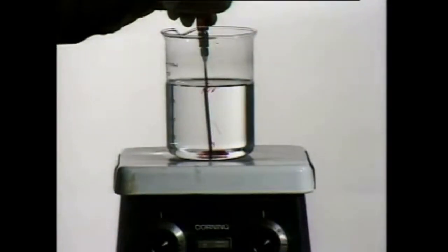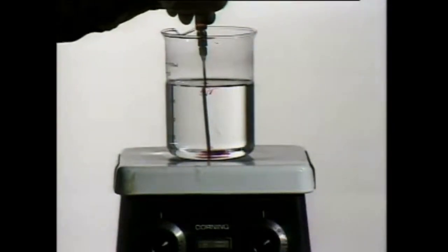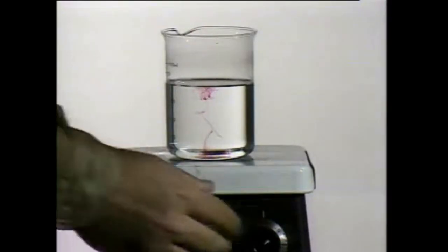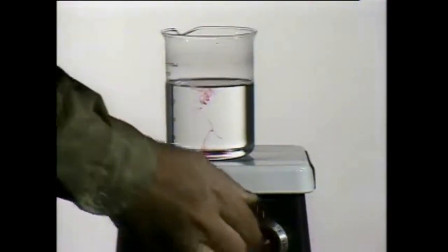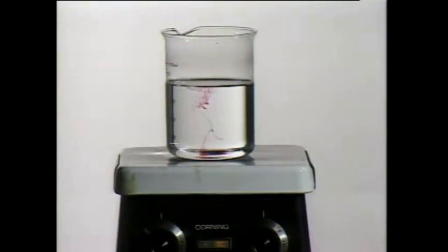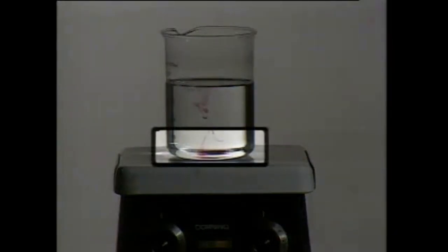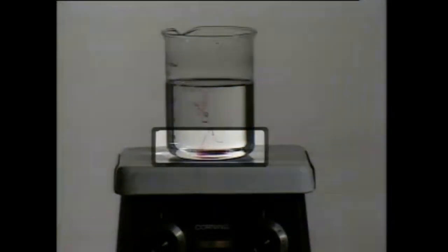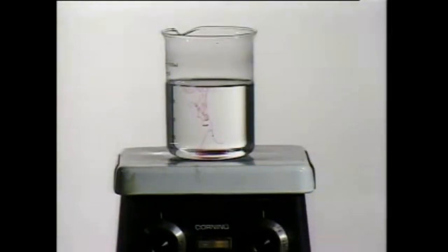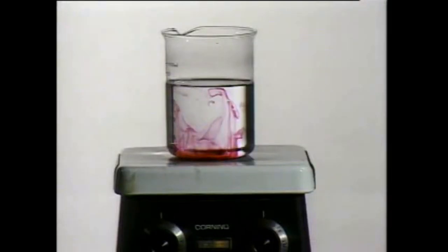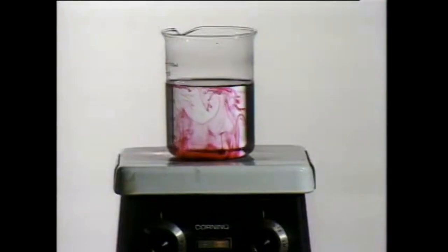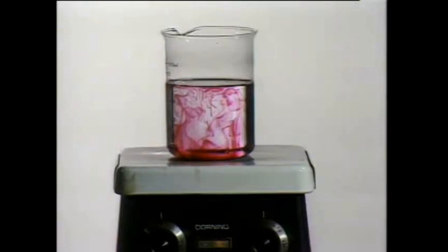We'll use this container of water and dye to show how natural convection works. As the water is heated, the water that's closest to the bottom is heated more than the water elsewhere. As the temperature of the water on the bottom increases, that water becomes lighter or less dense and rises upward. At the same time, the cooler water sinks to the bottom of the container. So during natural convection, as heat is transferred to the water, the difference in densities causes the water to circulate in the container. This circulation helps to transfer heat throughout the water.